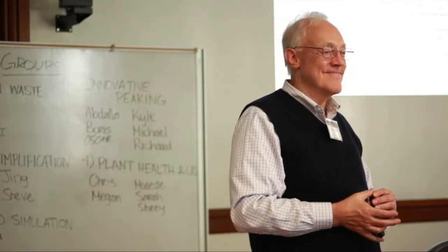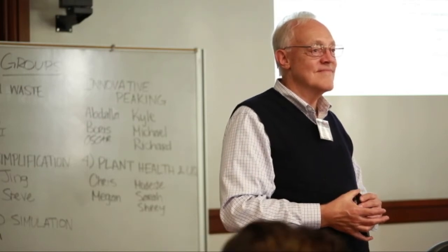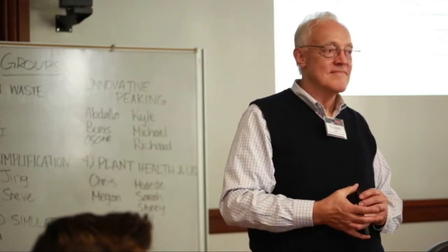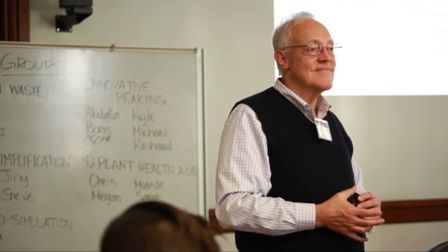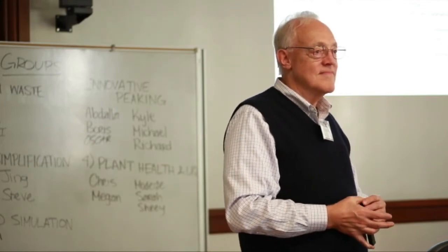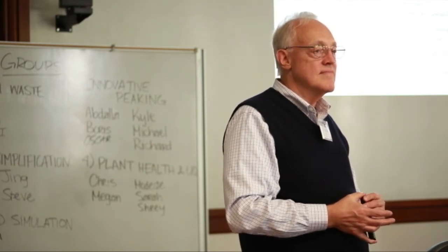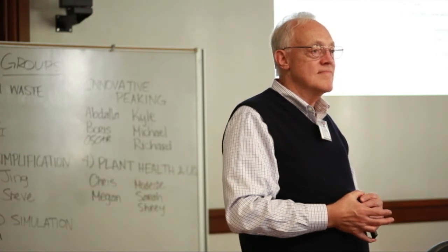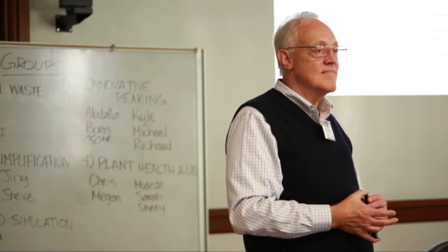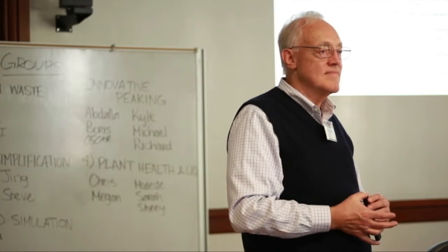But the reason I throw that in there is that when you look at the light water reactors, the bottom one is really interesting. You take the probabilistic risk assessment, and you list all of the potential failure mechanisms for a light water reactor, and you look at loss of coolant accident, whether it's a small break or a large break, like rod ejection accidents or reactivity insertion accidents. You start stacking them up, which one drives the probability of an off-site release and so on. You can then design those things out. And that's exactly what I worked on with IRIS at Westinghouse for a number of years, and this was before SMR was even an acronym we had.